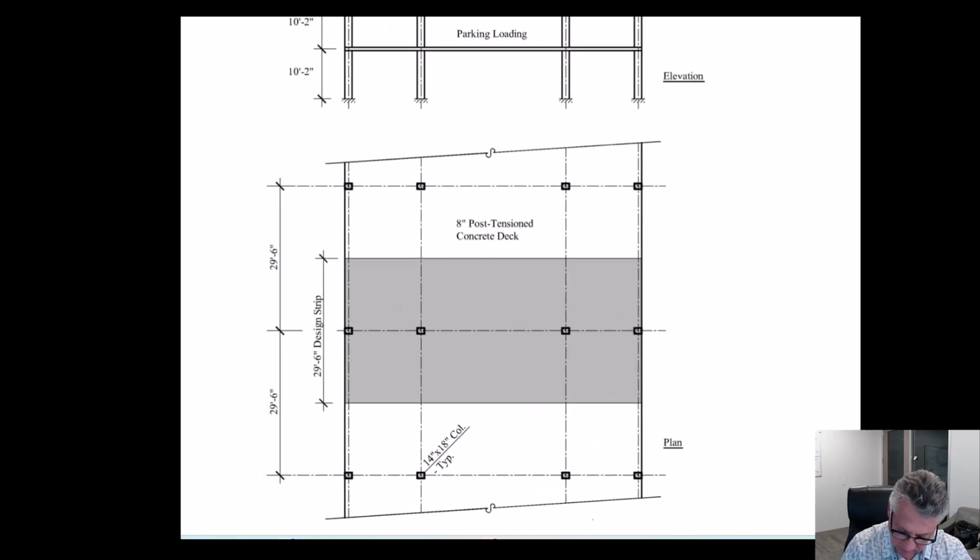We are going to look at an interior column, but the minimum is going to be based upon this area times the slab thickness, or this tributary area times the slab thickness. And whichever one is larger is going to determine the top steel in both directions over that column, not just in the direction that we're doing this analysis.